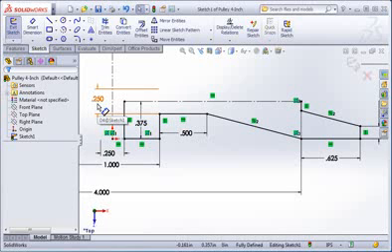The thickness in these areas is more informative than half the thickness because it directly describes the final thickness of the geometry. Notice that this dimension only defines half the thickness. Usually when you're designing a part, the design parameters define the thickness and not half the thickness. So let's change this dimension to a diametral dimension.